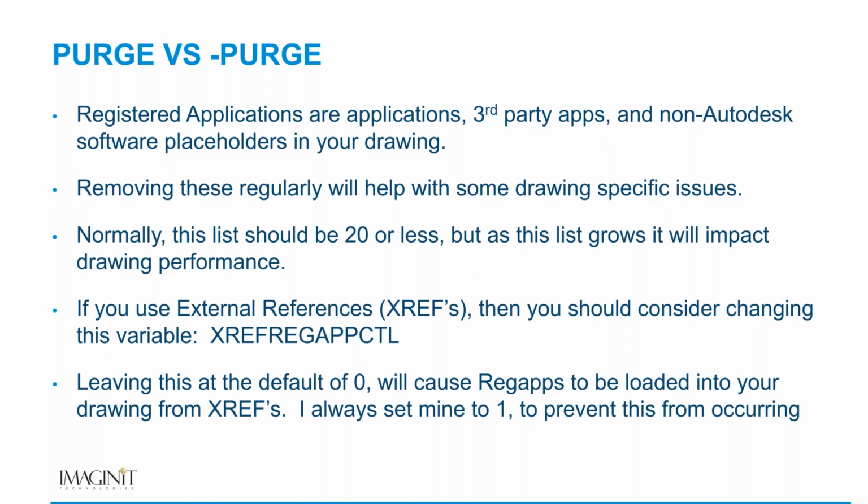So in most cases, none come across. On occasion, you'll have 1 or 2. This really helps keep your drawings clean, and this is that bonus item about this XREF regapp control. Always set it to 1. That's the best advice I can give you. It's going to help prevent you from getting a lot of these registered applications.